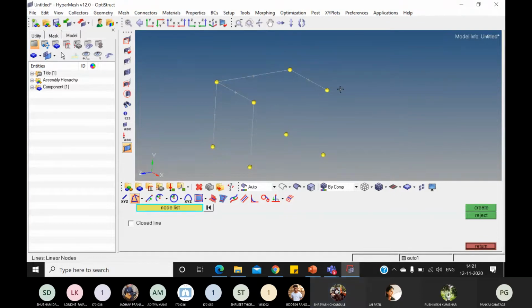I'll show you. There are some options. I'll show you in this one. Okay. This to this, I'll show you. You check out here first. Okay. This one, you have to give the coordinates. Coordinates are important. You can set the 0, 0, 0 anywhere and take a distance x coordinate and y coordinate. Suppose I want here. Okay. So here it is 0, 0, right? So x coordinate, let us take 100 and y coordinate is 500. Then it will be created here. Okay, I'll show you.